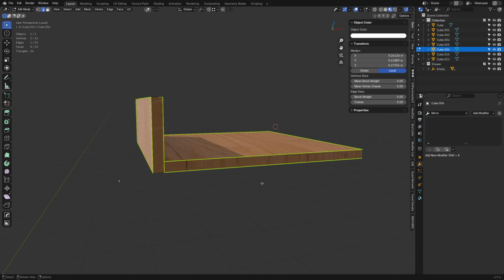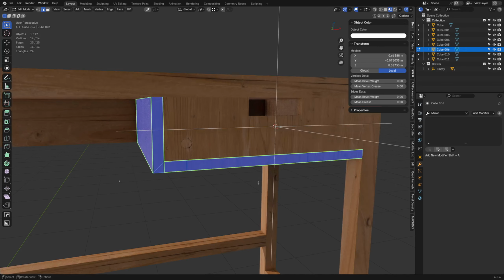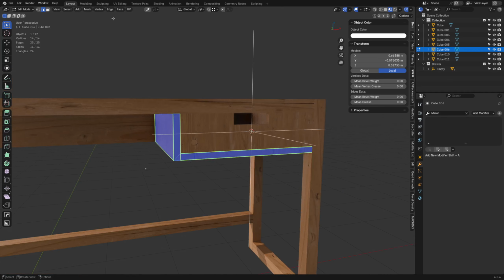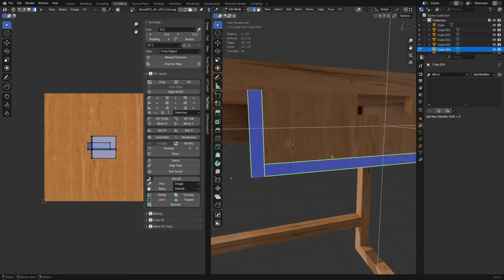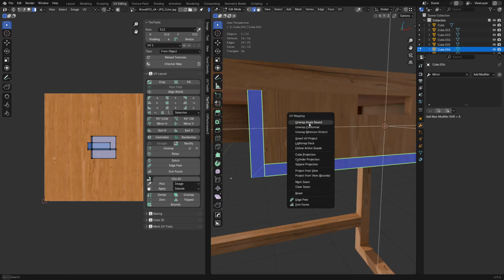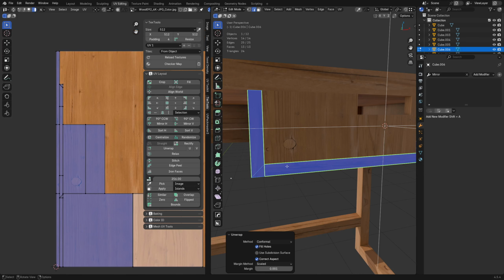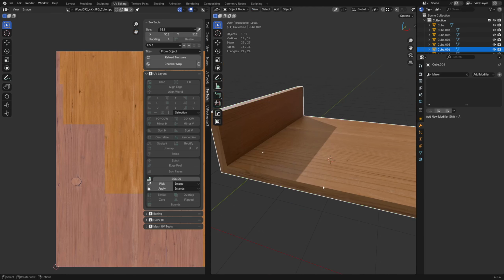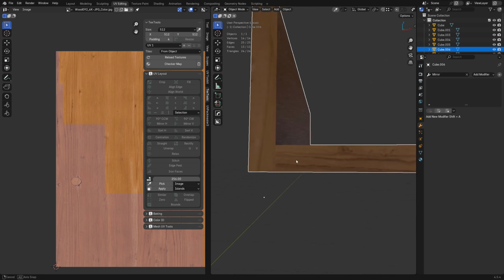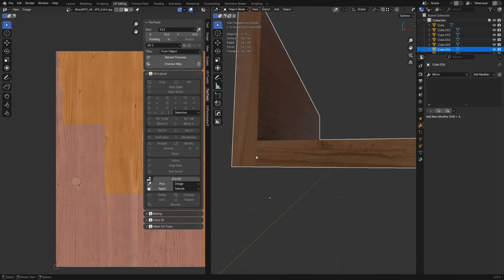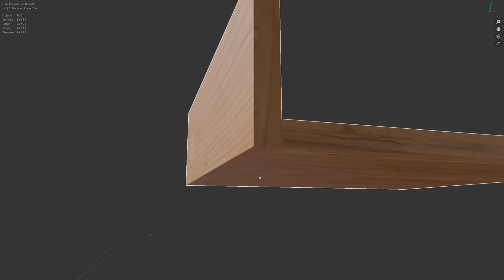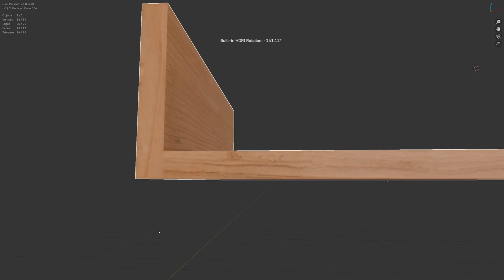But we don't do seams like we would if we are doing high to low poly bakes where every sharp edge gets a seam. You don't have to do that necessarily. So watch what happens here with this one. If we do U and we're going to do an unwrap conformal, it's going to lay out something like this right out. And that's exactly what we want, that behavior. So it's going to look like there's a little cut here that doesn't exist, right? That's the only thing. You can actually use a seam sometimes for styling purposes, right?